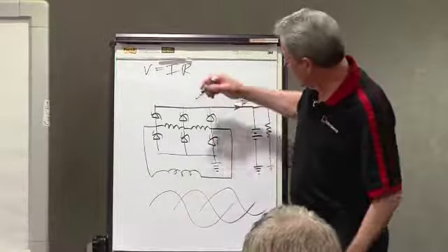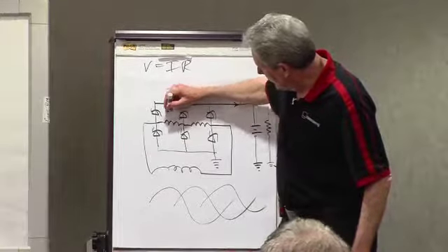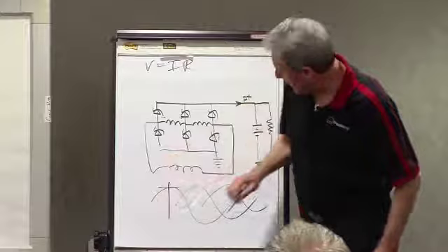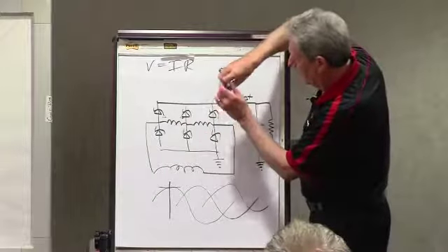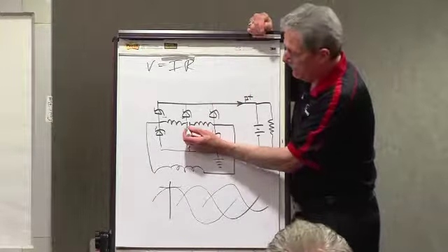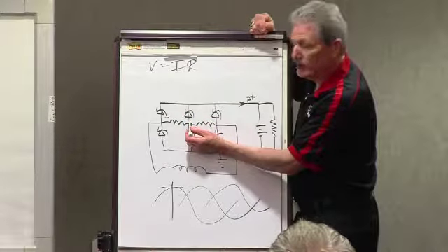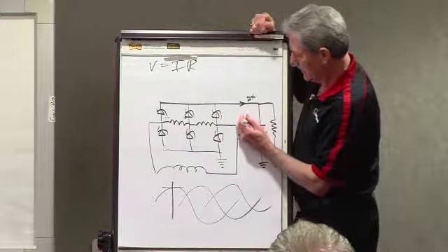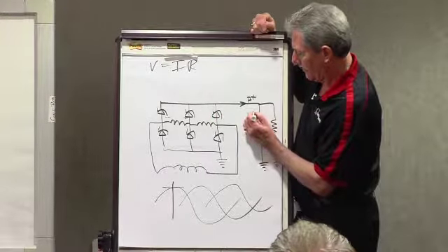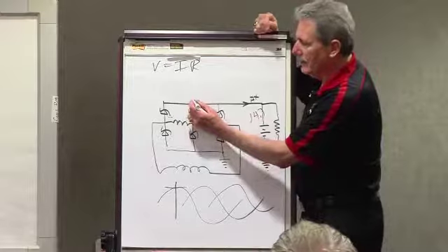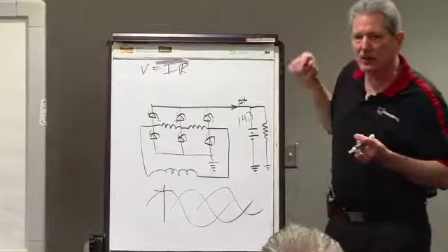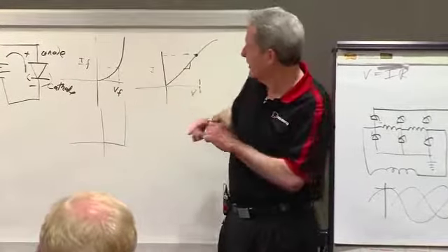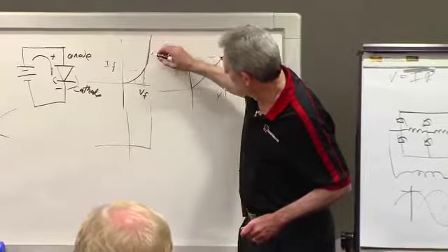Let's take this one as an example. At this point, the voltage is positive. So this diode is positive with respect to here. As soon as this gets 1 volt above B plus voltage, let's say that this is 14.7 volts. I told you earlier that it begins to turn on at 6 or 7/10. It's turned hard on at a volt.